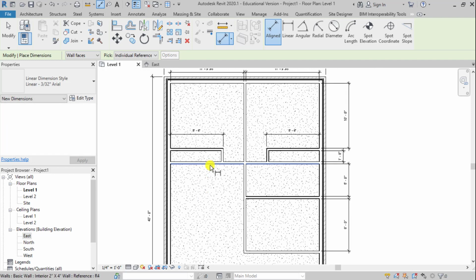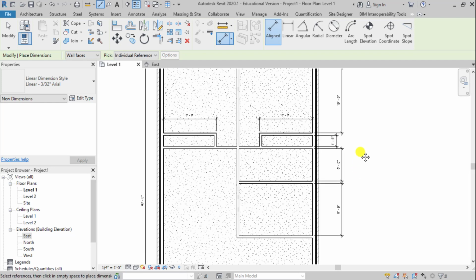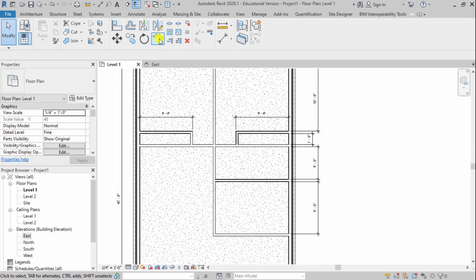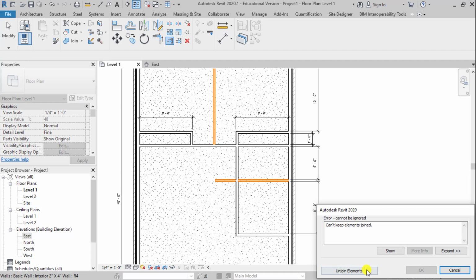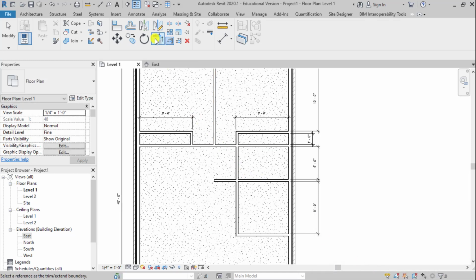and now I can see that I've got all of my dimensions, and the problem is this wall is in the wrong spot. I just realized that. Okay, no big deal. Pick our trim extend. That should be these walls, otherwise you have no way of getting into your bedroom. And then we can trim using this as our cutting edge, keeping this. We can unjoin our elements because these two will not be connected anymore. And we can trim and keep that.